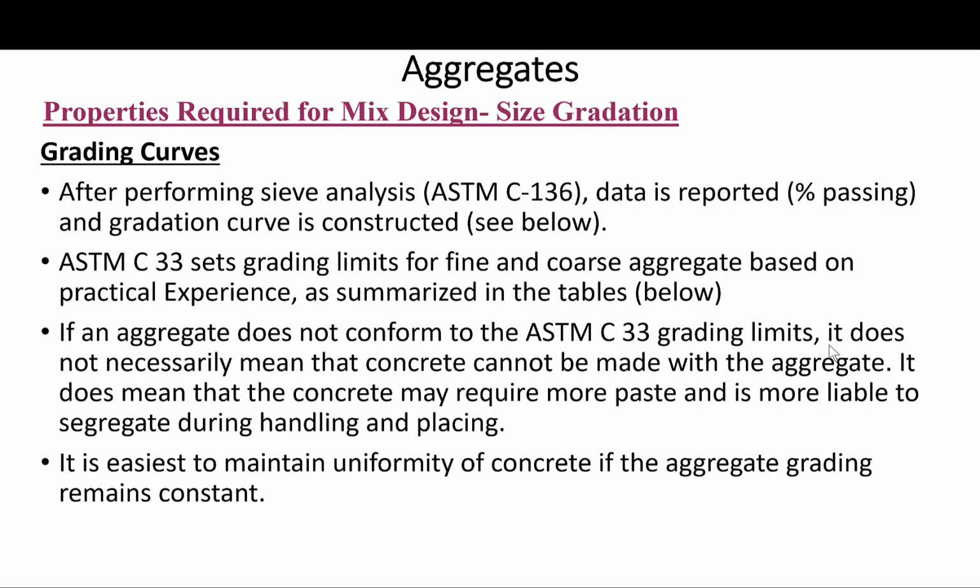Basically, when a sieve analysis has been completed, according to the provisions of ASTM C136, the weight of the aggregates retained on each sieve is expressed as a percentage of the total weight of the sample. This is then used to calculate the cumulative percentage retained on each successive sieve, or the cumulative percentage passing each sieve, as I will show on the next slide momentarily.